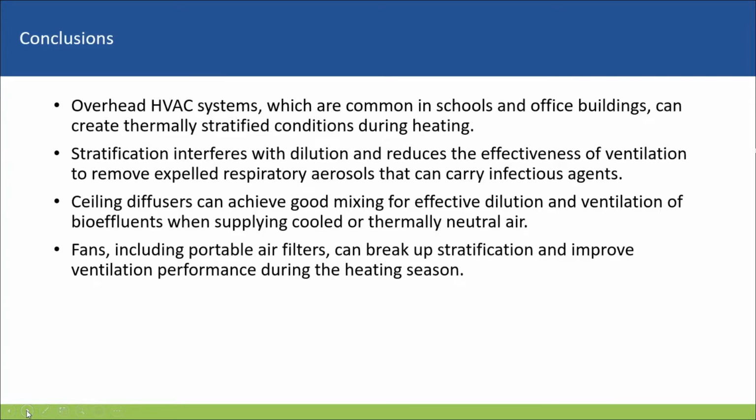So the conclusion of the study is that overhead HVAC systems, which are common in schools and office buildings, can create a thermal stratified condition during heating, and the stratification interferes with dilution and reduces the effectiveness of ventilation to expel respiratory aerosols that can carry infectious agents. Sealing diffusers and achieving good mixing is effective for dilution and ventilation of bioeffluents, which supply cool or neutral air. Including portable air filters can break up stratification and improve the ventilation performance during the heating season.